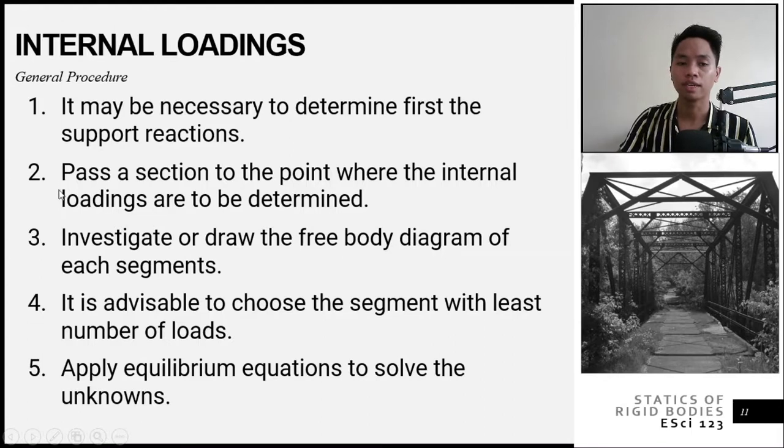Okay? Then second, you pass a section. You cut where you want to place it, at the point where you want to know the internal loadings. Then after that, you investigate. Or it is safer to draw each segment, but usually you just investigate. You investigate which segment has the least number of loads, because it is easier to solve. You can solve quickly if there are only a few loads.